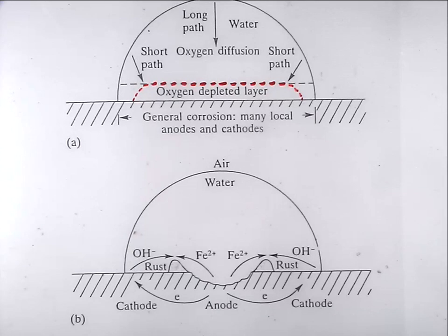So it's a horizontal tube, and there was solution sitting in the bottom of it, but it wasn't full when it was parked up. The pits, and this particular one hasn't actually pitted right through, but we've got some of the same pipe that had, which is why we've got the tube in the first place. So we've got our tube, it's that orientation, we've got some solution in the bottom of it, and the pits have developed in this sort of position, just under the water line.